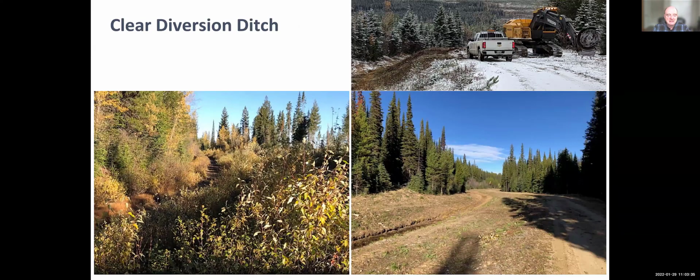And here's another example. It's a diversion ditch linked into a storage reservoir, but it's when it gets really filled in with willows and alder and birch and poplar and other trees, to come in there with a big weed eater and clean it out does a really good job. So you go from totally overgrown to something where it's really easy to inspect, and you've got full drainage capacity in that ditch.